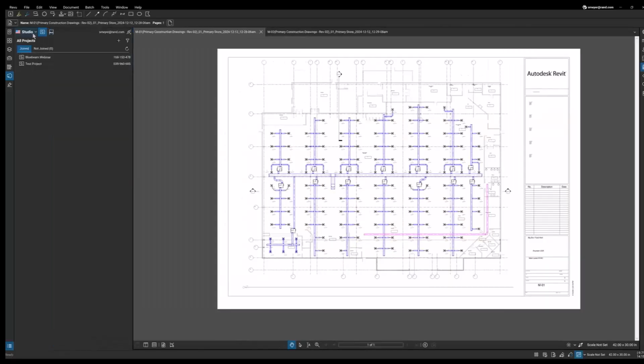So you can see up here, it says Studio. I would be able to sign in directly using my Bluebeam login. And then from here, I have my Studio projects as well as my Studio sessions. Now, these are two separate things. If we are working on a project, we can check things out, we can take things down, we can use them elsewhere. Sessions are going to be live. That is where we're going to be actively collaborating with other teams on projects at the same time.